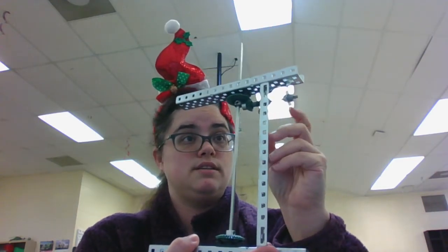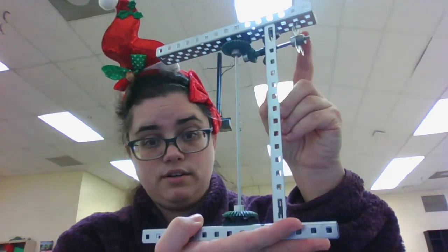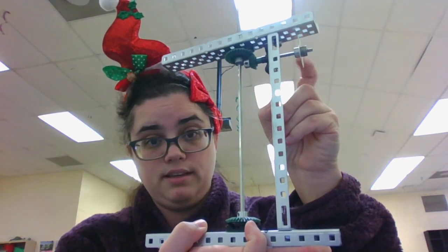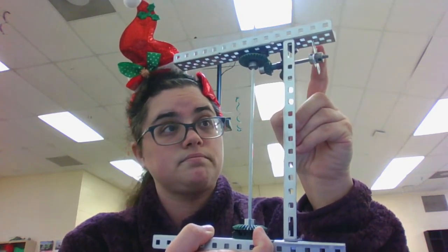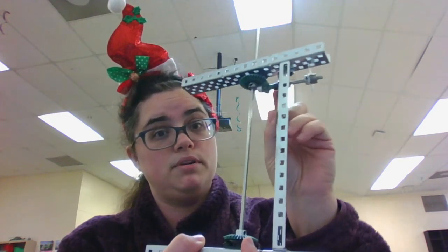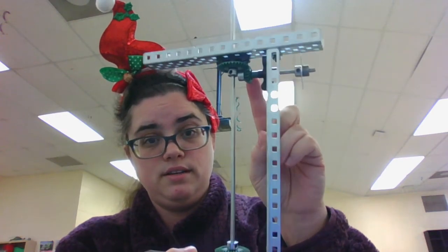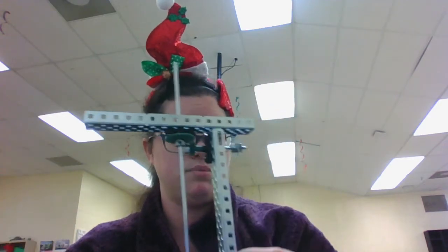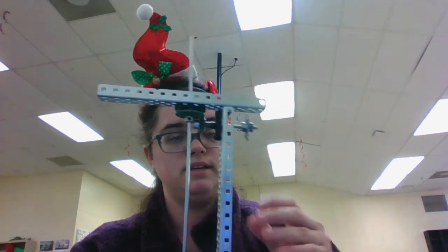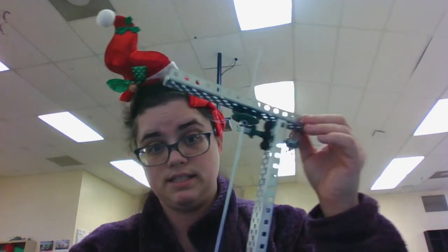Because if you turn up here, I don't know if you can see, the shaft is moving. You can tell by looking at the gear at the bottom here, this bevel gear. And the interesting thing to do would be maybe to put the same gear, another one of these little bevels at the bottom, because that would make it have an equal speed ratio the whole way down, equal input-output speed ratio and torque ratio. But yeah, this is definitely one of those where if I shake it a lot, it's probably going to work the nuts loose off the bolts.